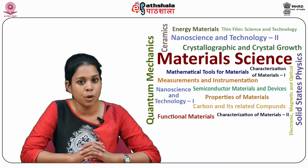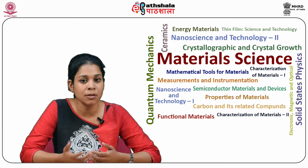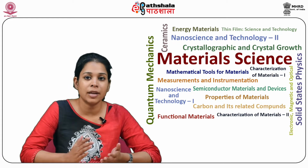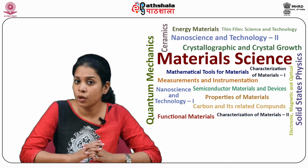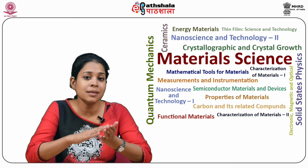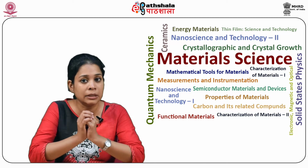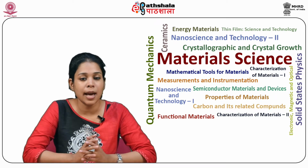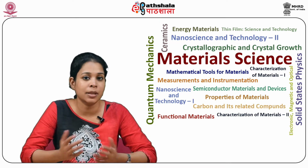These impurities may act as centers of polarons, species of electrons that create a small region of local polarization as they move from atom to atom. Electronically conductive ceramics are used as resistors, electrodes and heating elements.